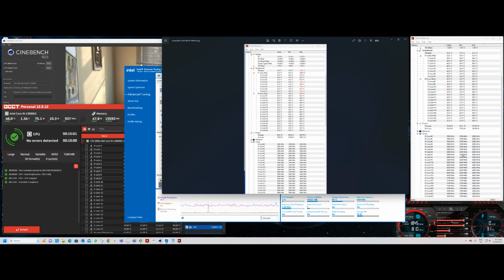But in a case like that, normally the KS outperforms slightly, not a huge difference. In my case, I was able to undervolt and still keep it at almost the default settings. The only difference is that instead of 2 or 3, I was able to get to 6,000 on all cores. And I believe I can still slightly increase it, maybe to 6,100 or 6,200 megahertz, which I'm probably going to do slowly. But I did spend a considerable amount of time overclocking and stress testing, making sure I got the stability, and that's how I was able to go for that.